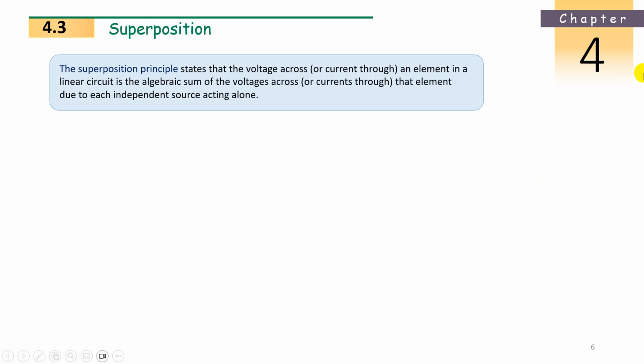Second step, again put the second voltage source and remove all the remaining ones. Then solve the complete circuit in terms of equivalent resistances, find the current with Ohm's law, then distribute it in all the branches. Like this, as per my example, 5 voltage sources means 5 times we have to solve the problem, one voltage source at a time. So we'll get all 5 different currents. Now sum them all. That is nothing but superposition.